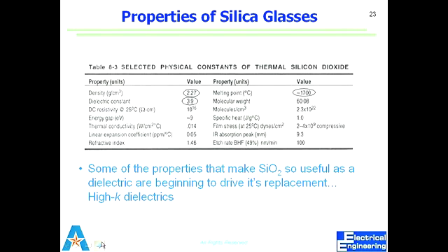Dielectric constant, yeah, 3.9, we don't do it. So resistivity, energy gap, conductivity, expansion, these are all physical or mechanical or electrical properties which are very conducive for silicon. If thermal expansion was way different than silicon, we would have stress issues, right? What would happen if you have stress between two films? They separate, or you crack the material. It can crack the material, right?